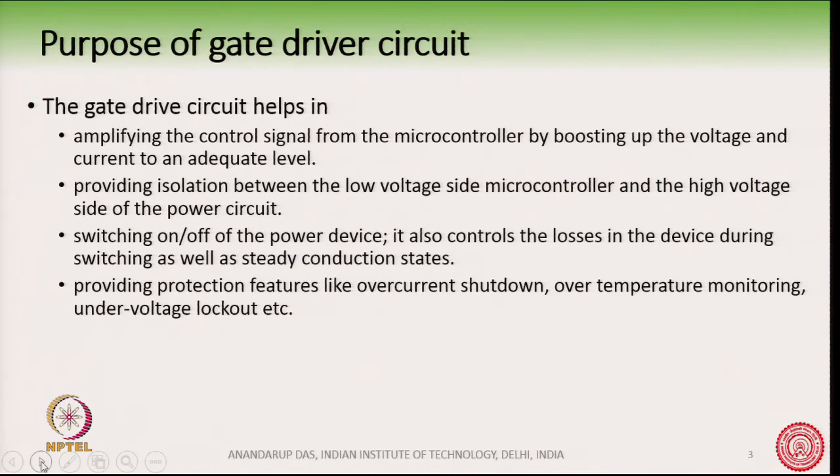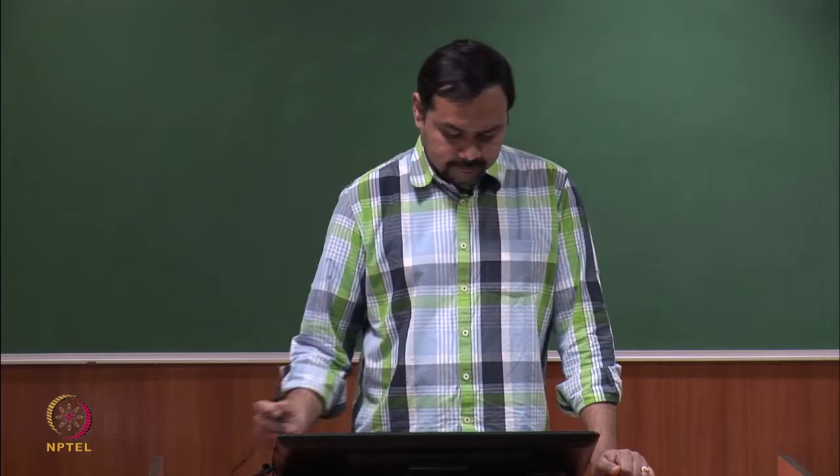Modern day gate drive circuits come with a gate driver IC, and they can provide a lot of additional features, and most importantly many protection features like overcurrent shutdown, over temperature, under voltage lockout, etc. These protective features provided by these gate driver ICs are often very useful while running the converter, and as a result the gate driver circuit is one of the most important and integral parts of any power circuit design.